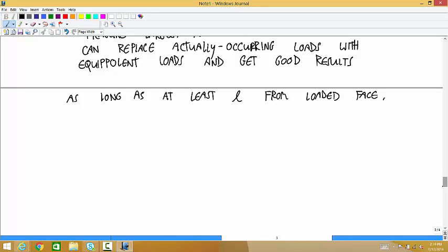I wanted to say one other thing too. Before I do that, any other questions about St. Venant's principle? It's really lucky it works this way, because if it didn't, say you apply 5,000 newtons of tension to this body, and changing the way you applied that 5,000 newtons of tension affected all of the stresses noticeably all the way through the material, there'd be no benefit to doing hand calculations.